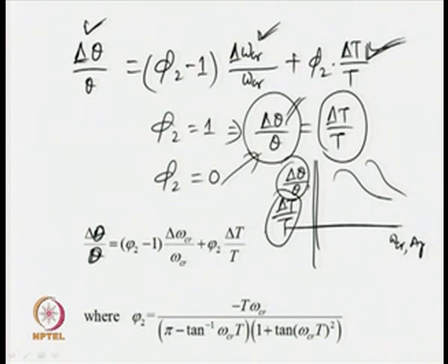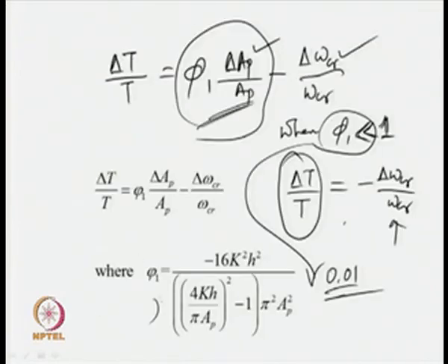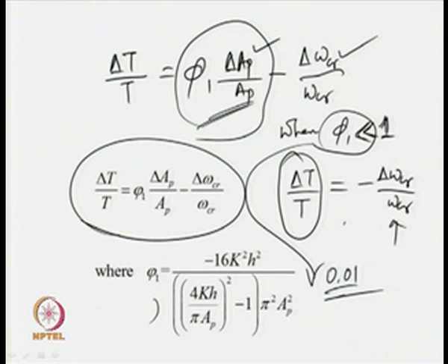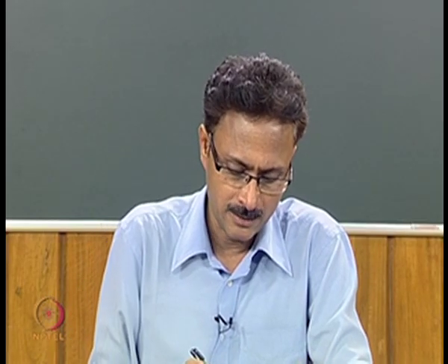Okay, that is how the two expressions are quite powerful, and similar expressions can be obtained for the analytical explicit expressions we have obtained for the identification of first order plus dead time and second order plus dead time transfer function models.